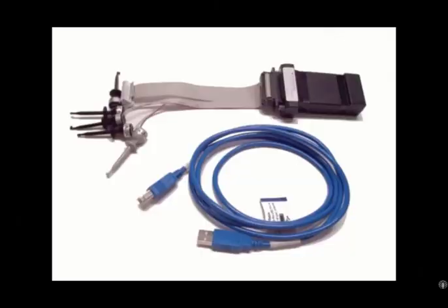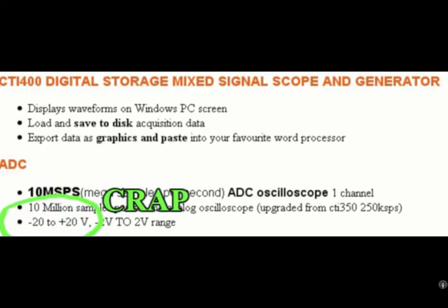Nowadays, you can also get cheap USB-based scopes that you can plug into your laptop. Generally speaking, I stay away from these just because in case you connect something wrong, you don't want to risk frying your laptop. Also, standalone oscilloscopes tend to have higher ranges of voltages that you can measure. Now, I'd only get a USB scope if you seriously cannot afford a better standalone scope.